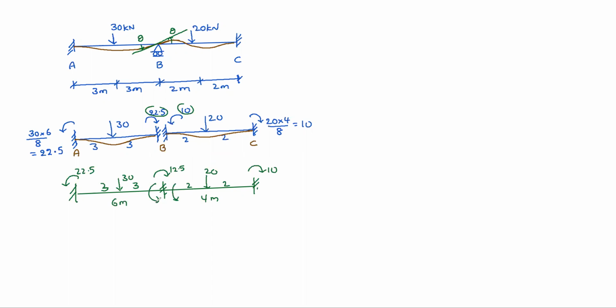So let's see anti-clockwise for like this something and like this something. Suppose this is some x amount. Let us assume this is y amount. So that means x plus y must be equal to 12.5. So how much is x, how much is y? How to apply that one? What ratio we need to distribute? We need to distribute the 12.5 in the stiffness ratio.